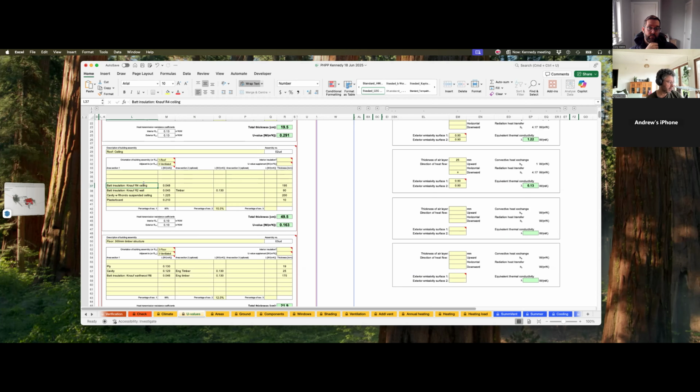So that 200 mil service cavity, going from the top down, you've got your R4 bat, your R2 bat, then you've got your airtight layer underneath that. So underneath your ceiling joists, then you've got your service cavity. And then you've got your plasterboard. I use 13, don't you, Corey? Yeah. So because all your services are in your service cavity, we don't have to be so concerned about what I just said up top.